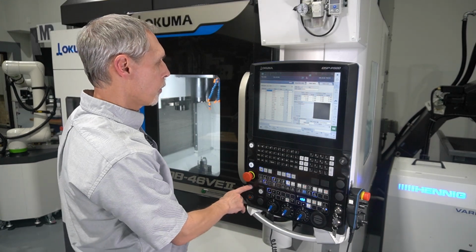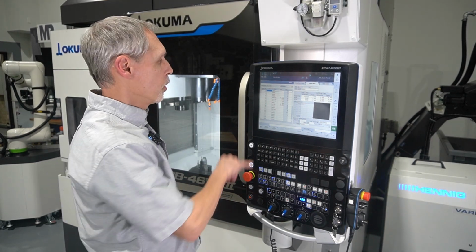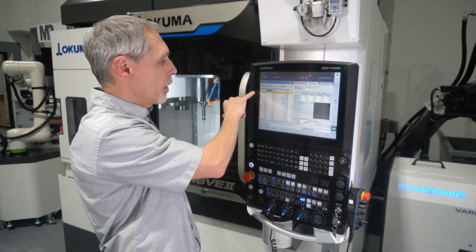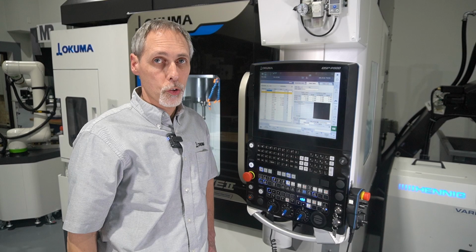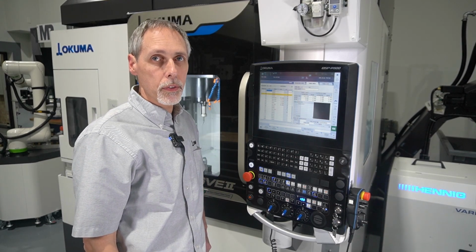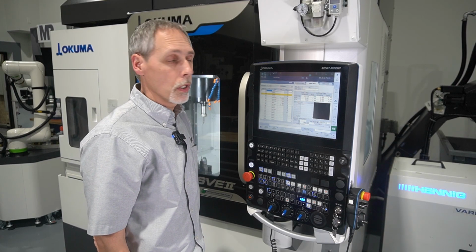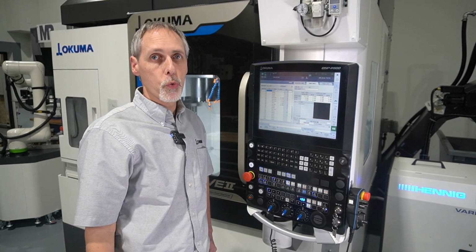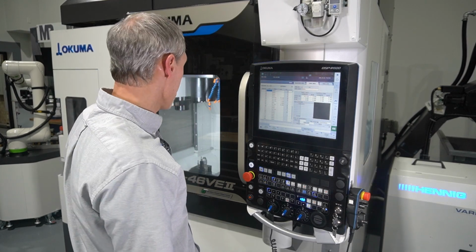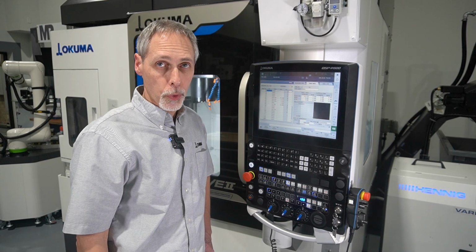So this time here when I run it, should see tool 155 will come up as being the active tool, and it does. So now it's going to run that tool until it expires. So we could do this over and over again as many times as we want, as many spare tools that we've set up. It's limited to the number of tools in your tool chain. So that's how the function works.